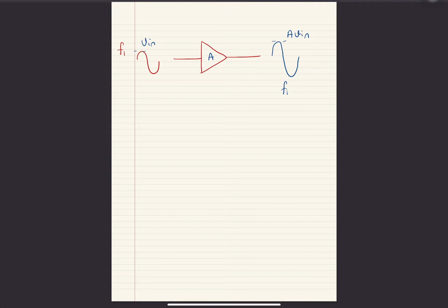And you want to have this thing for a range of different frequencies. So when you have different frequencies f2, f3, f4, at the output, what you expect is the output should be the combination of all these inputs, let's say Vi times A. You want to have all of them to be multiplied by the same gain. So that's the definition of linearity. In nonlinear amplifiers, the gain changes depending on the signal amplitude or depending on the signal frequency.